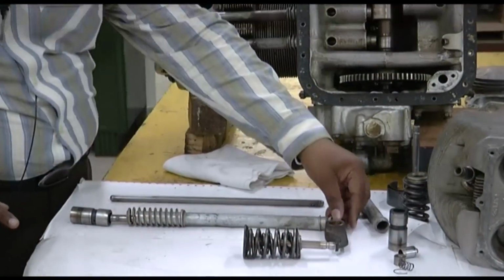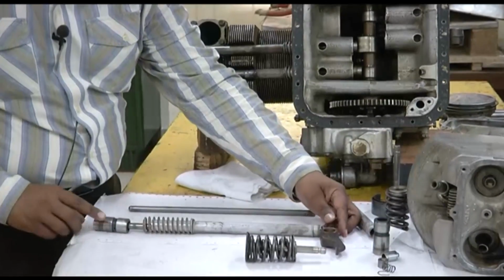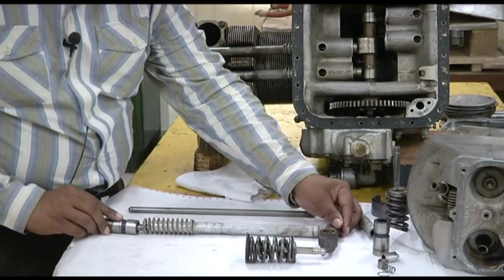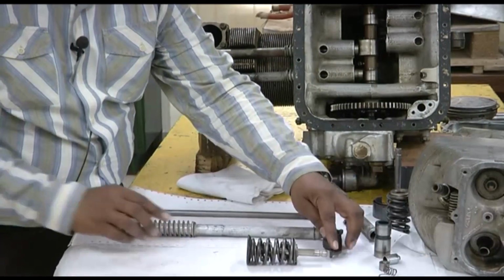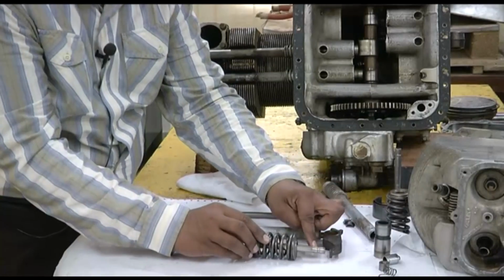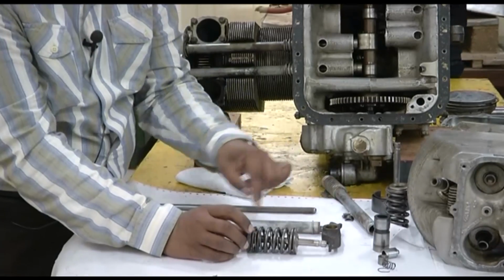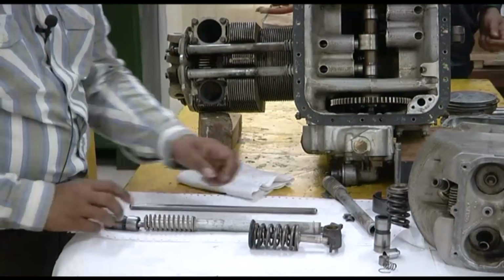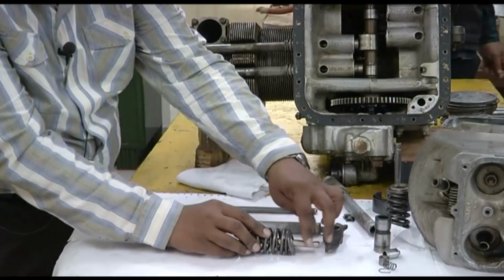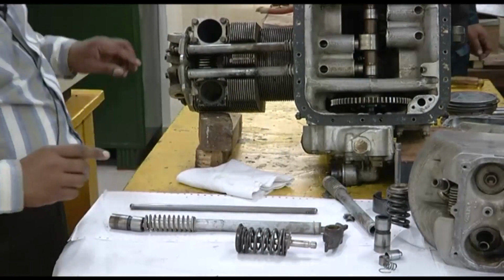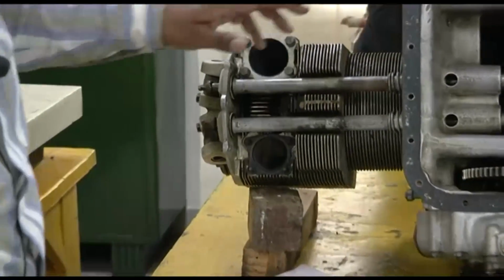Now here you see this is your rocker arm which is being pushed by the push rod. So when it is pushed by the push rod here, this rocker arm goes down. The other end of the rocker arm is connected to the valve like this. This is your tip of the valve and this is your valve, and when this pushes it from here, this rocker arm goes down and this valve goes down against the spring pressure. So I'll show you here on the engine. We will try to turn the engine and show you.